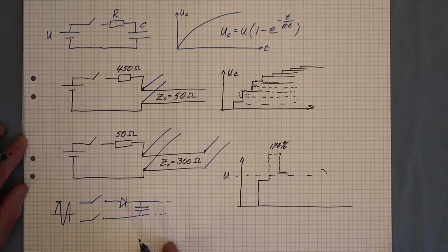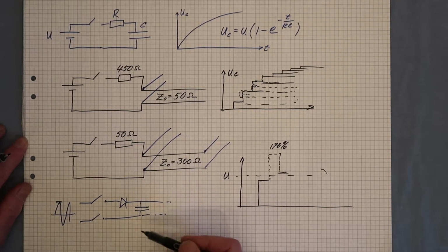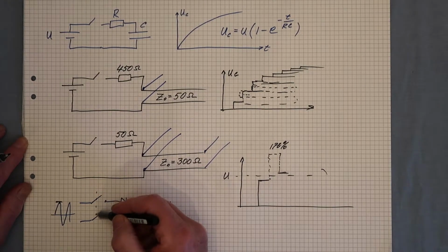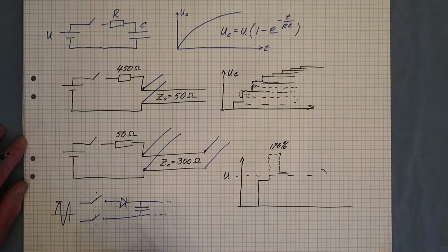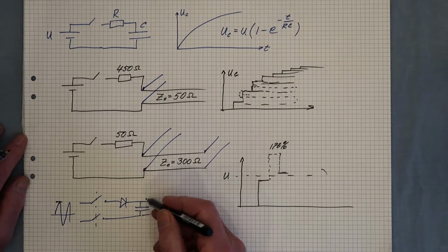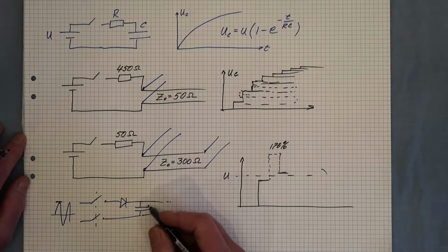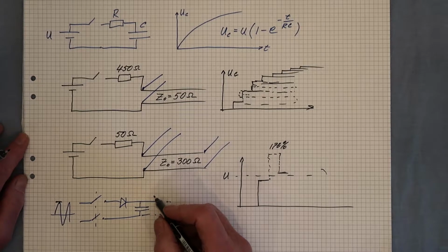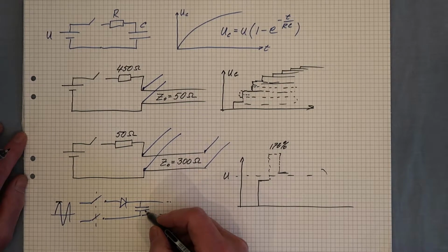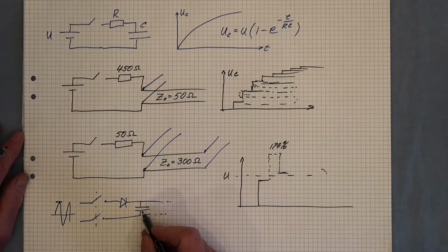Usually, electrical equipment, the power supply will break down at power on, and that's because at power on the voltage within the capacitors is almost twice the mains voltage, and usually the capacitors are not chosen to sustain that very high voltage.